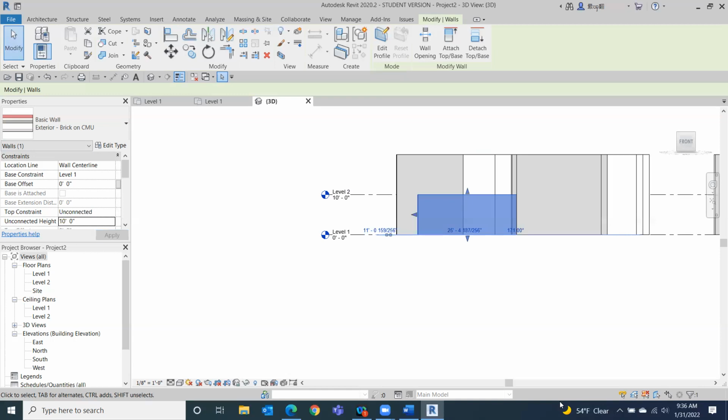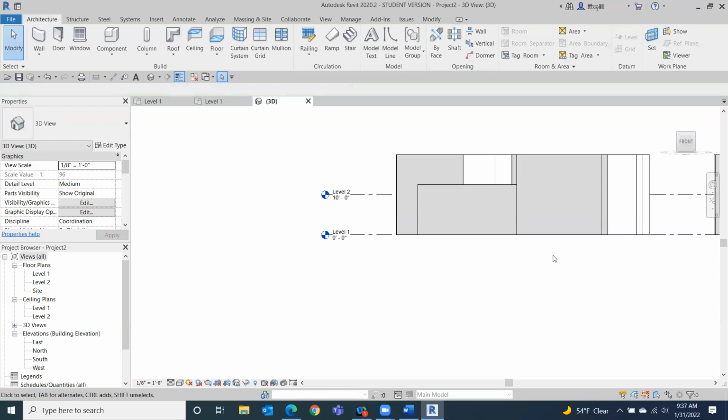What's nice about Revit is that if I wanted that to be like 100 feet, 2 inches, I don't have to worry about doing all the symbols all the time. So if I wanted to change that back to like 12 foot 6 inches, I could do 12 space 6. And it'll know to put it at 12 foot 6 inches. So it's another little shortcut for you.